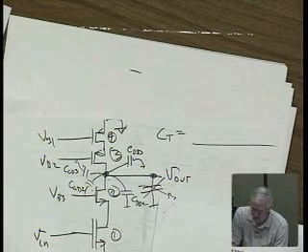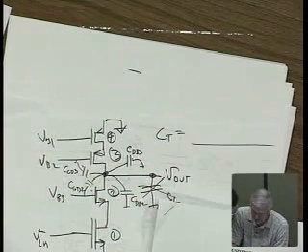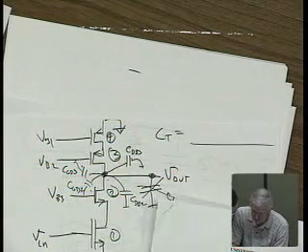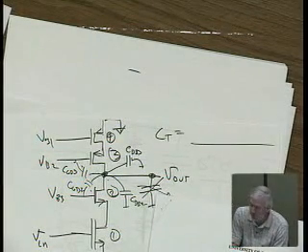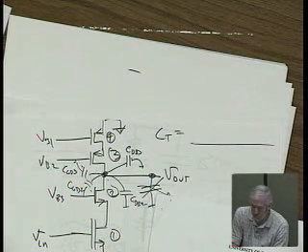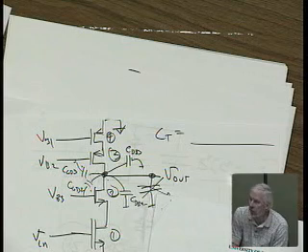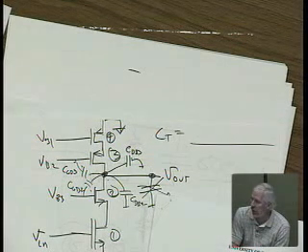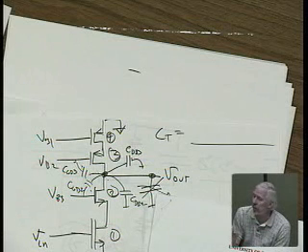What you said in the last lecture, what about the relative values of CD, C mu, or C gate, for simplifying the circuits? C gate is generally much bigger than CD. C mu is usually the smallest. CD is kind of second, and C gate's biggest by far.